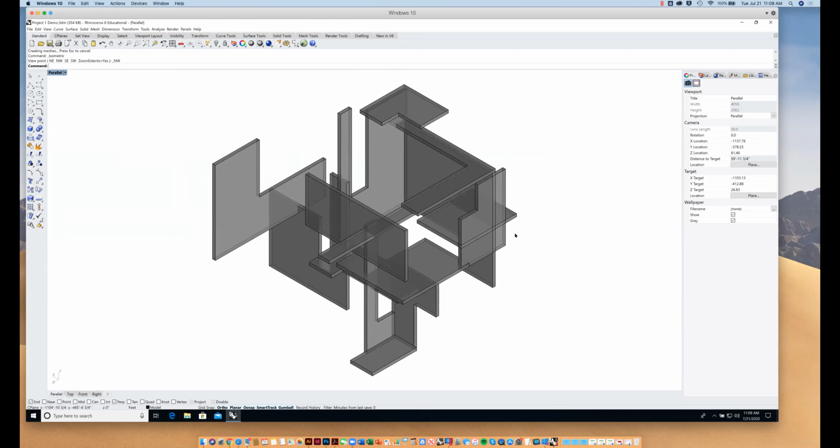There's a couple of steps that we're going to do today, and then some steps that we'll repeat tomorrow and then build off of tomorrow. But I want to show you some of the additional modeling you're going to have to do in Rhino. And then I'll show you how to export that stuff to a file format called SAT that you can bring into Revit. And then we'll do some initial steps in Revit with some of the surfaces that we created and creating curtain wall. Tomorrow we'll go over Revit again, but we'll go over the paneling and make a custom reveal profile, and then start to add reveals to walls for the aluminum paneling.